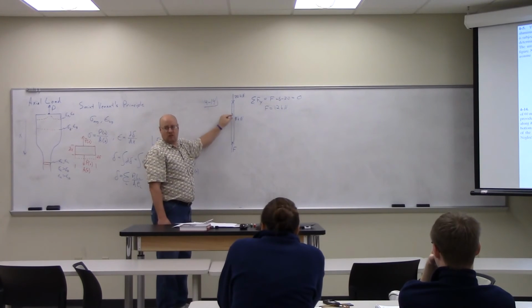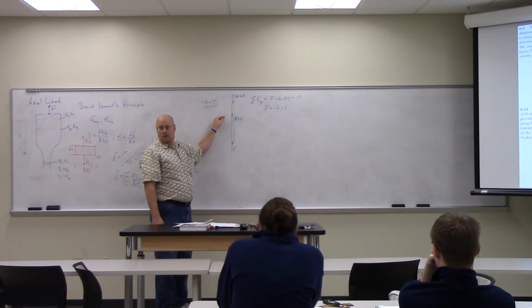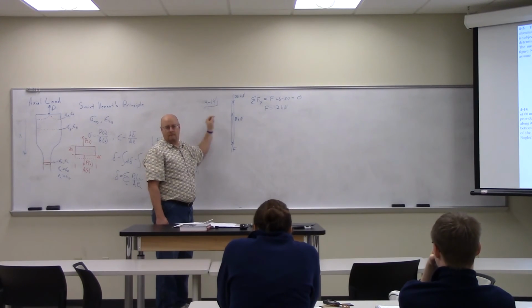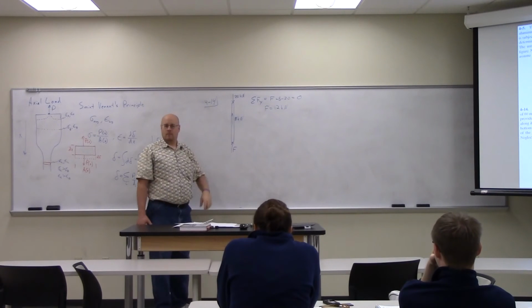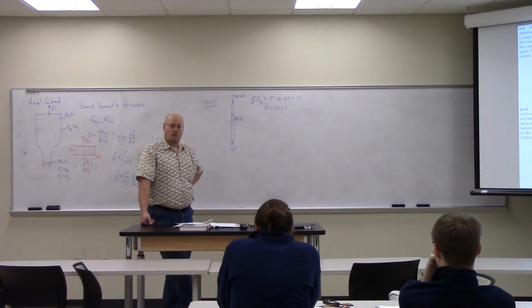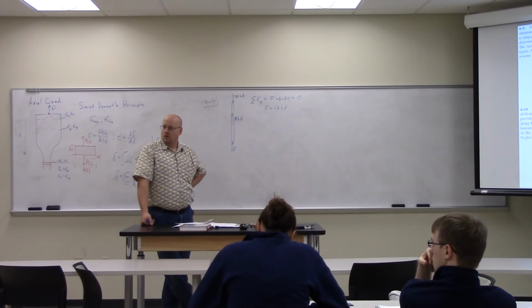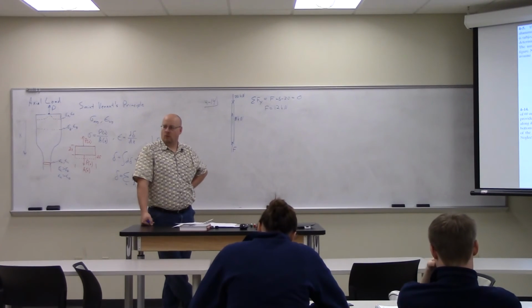If I take this little section out here, it's going to be, halfway, 18? Yes. So the friction is distributed uniformly. The top half experiences 4 kilonewtons of friction, the bottom half experiences another 4 kilonewtons of friction.